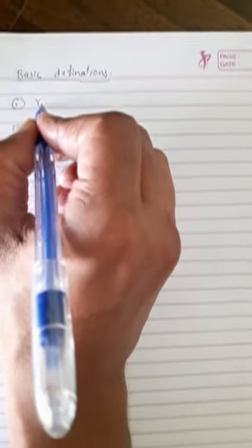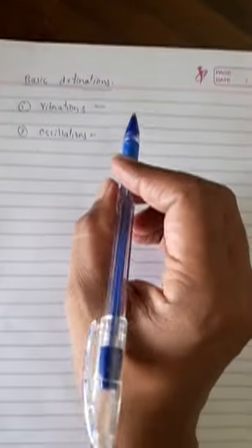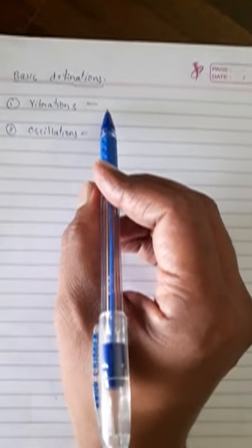So, first comes vibration. Always remember earthquake forces are cyclic in nature. They produce oscillations, to and fro motions. So, with to and fro motions, two types of definitions come into the picture. One is vibration, second is oscillation. Both indicate to and fro oscillatory motions. But if there is deformation of the structure during reciprocatory movement, it is called vibration.